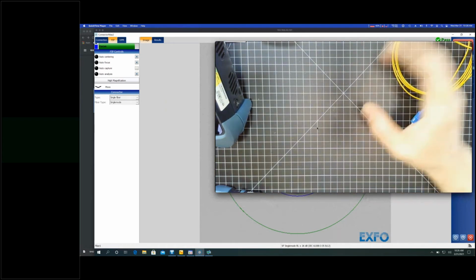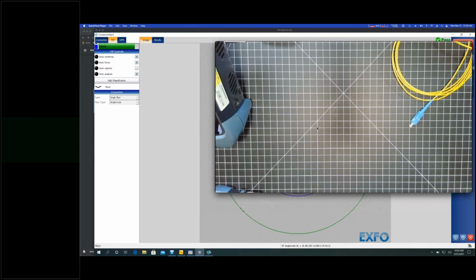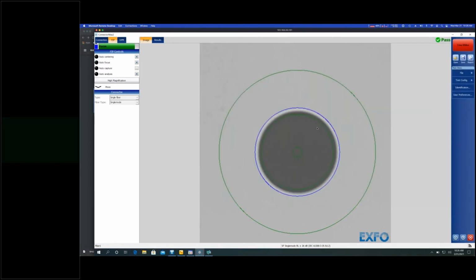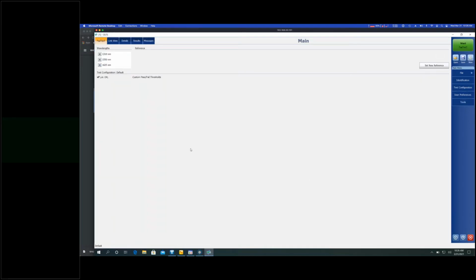But if you're installing plants, and it's brand new, what has become the industry standard is an optical loss test set, which, excuse me, over here, for EXFO is either the FTB or the Max Series 945. Essentially that consists of a power meter and a source in one unit that couples with a power meter or source in the other unit.